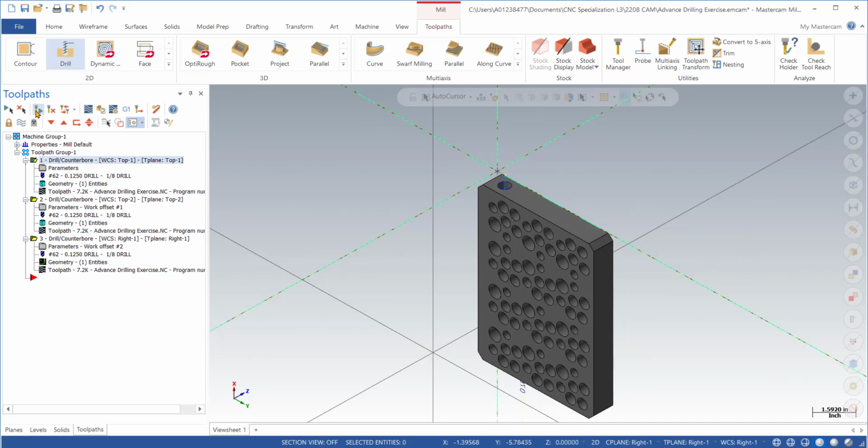All right. So basically now it will give us a different work offset for the side hole, and yeah, I can just set up a third vise, and install that plate the way it is showing on the screen with that orientation, pick that corner, and go from there. So let's just now post all three of them together and then see.